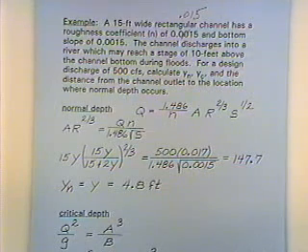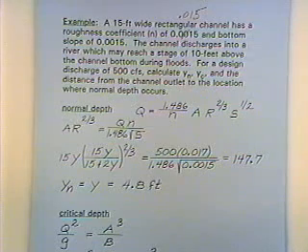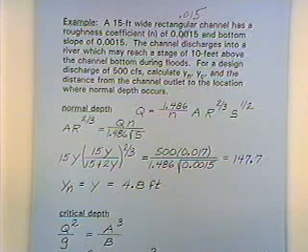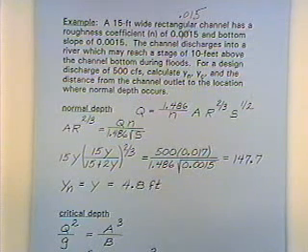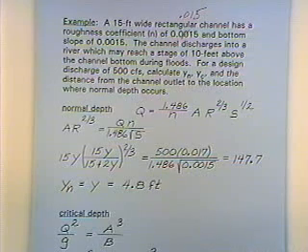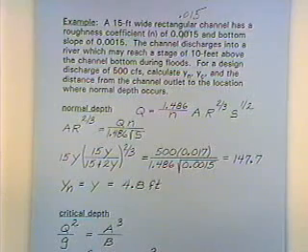So one question right offhand: are we going to have a hydraulic jump? Will the flow just be uniform until we get almost to the river and then have a hydraulic jump? Or will there be a smooth transition over a long distance, half a mile, 2 miles, a very smooth transition from the normal depth to the 10-foot depth in the river? To answer these questions, we need to know what the normal depth is and what the critical depth is. And so we'll just compute them.